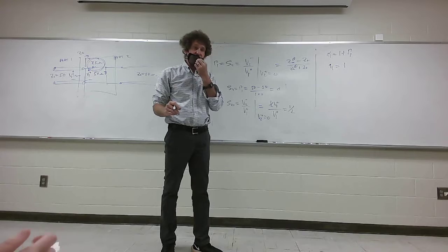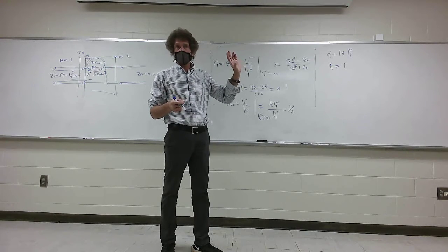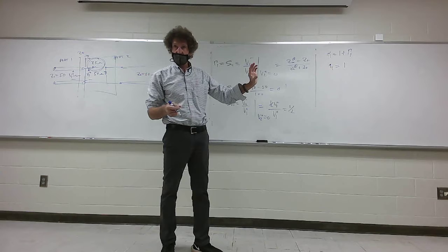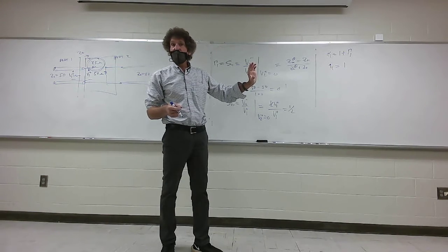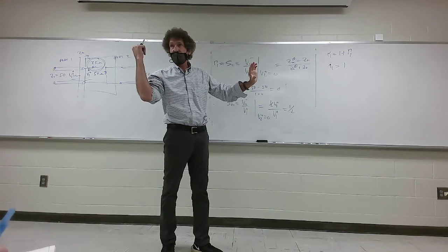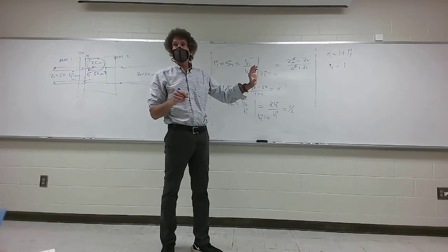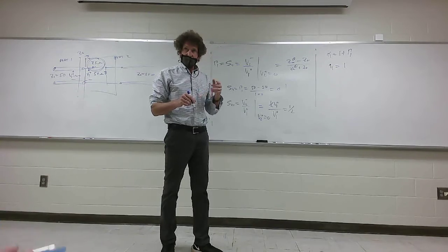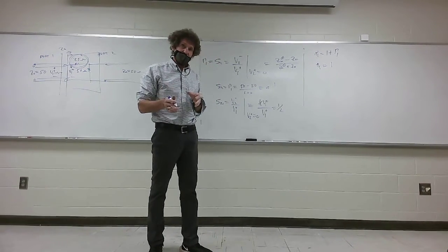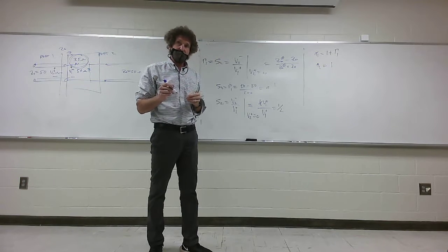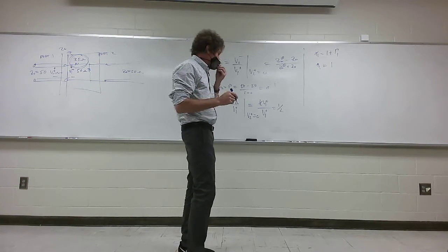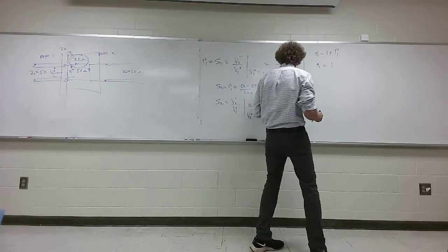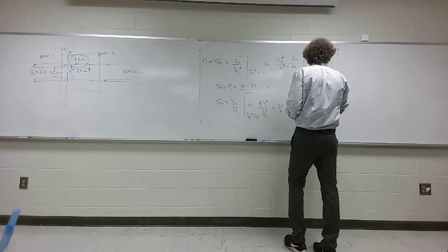That's the forward voltage gain. Whatever voltage comes into port 1, half of it will come out of port 2. Y'all follow me? Good question is what happened to the rest of it? It was dissipated in heat because of the resistances. Now, if you had inductors and capacitors there, you would never have real power dissipated. All right? But there could be a phase change so that the output voltage will be slightly different in phase and magnitude. We'll get to that later. I'm just letting you know that's where that power went. So that's 1/2. I've got S11, S21.